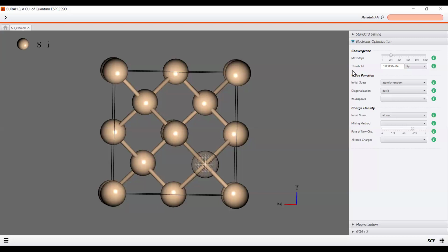So in this quantum, is it energy minimization? Yes. In Quantum ESPRESSO, minus 7 is the default, but I am using a smaller value because we have to run quickly. Okay, we have to see the result also here. So I put 4. 4 is not good for the optimization. You have to put minus 7. But here I just put 4.